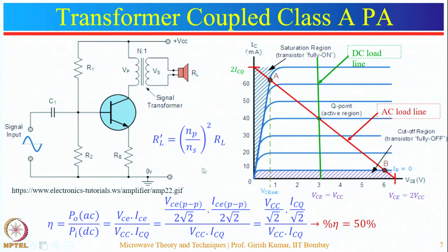Now, if you see here, if the signal is absent, in both the amplifier configurations of class A, the current will pass through this transistor. So, it will continuously dissipate heat. That is one of the disadvantages of class A configuration, that a lot of the power is dissipated in the transistor. Now, this configuration is also not desirable because the transformer is relatively bulky and frequency sensitive. So the frequency response is not very good. If the transformer is used for very good quality, then it becomes expensive. So that is why this configuration is not used.